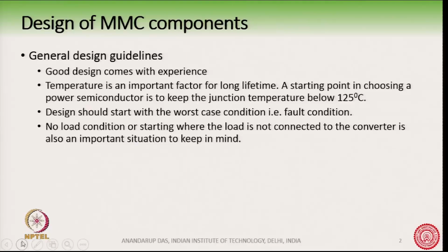Now, when you design a system, it is very important that you take care of the temperature. Temperatures are very important for long lifetime operation of the converter equipment. So, when you are in the industry, we generally follow the Arrhenius rule.